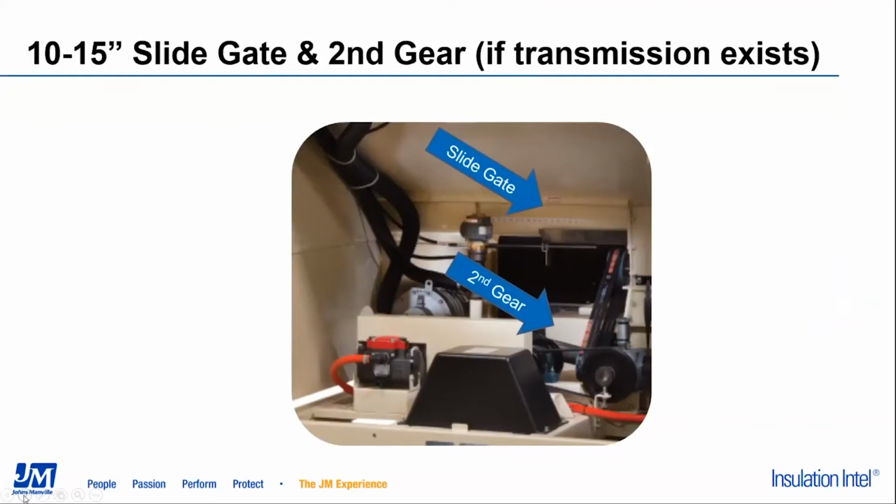If our material flow is light, we will open the gate in small increments until we achieve the desired result. If the bag is heavy, we close the gate slowly until we hit the target. At this point, I would recommend marking where your gate and air bypass are set. This way, future setup processes will be much quicker and easier.